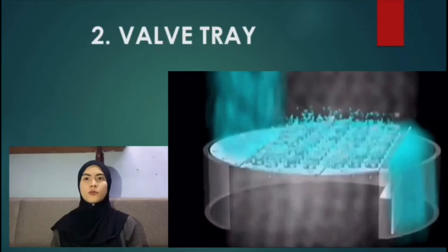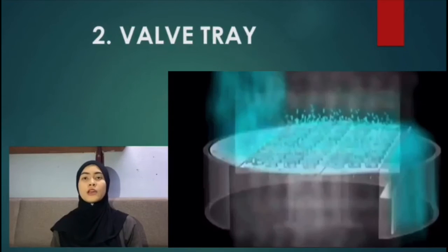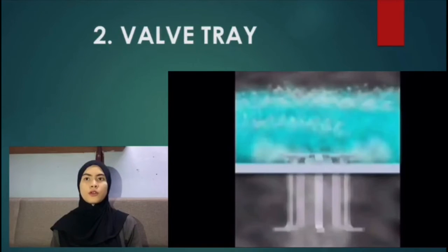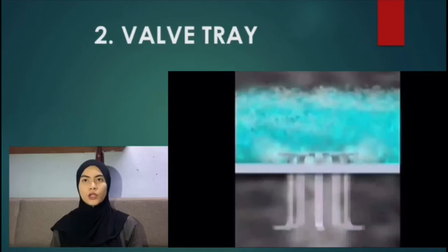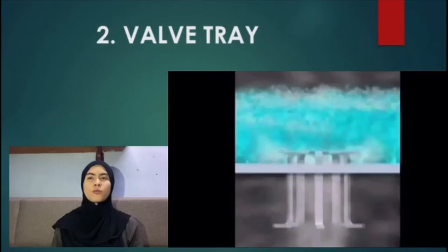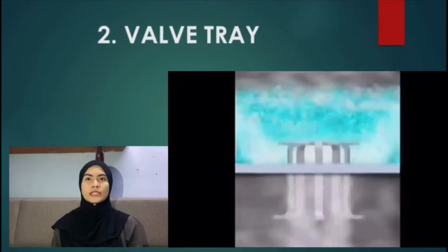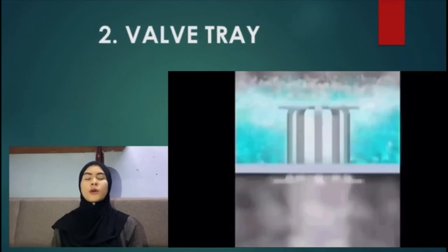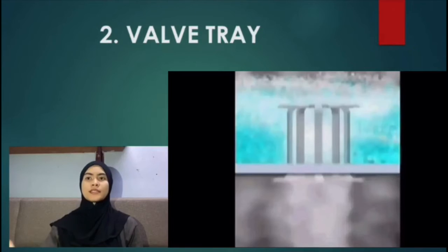each opening, providing a variable open area which is varied by the vapor flow, inhibiting leakage of liquid down the openings at low vapor rates. Hence, this type of tray can operate at a greater range of flow rates than the sieve tray, while costing only about 20% higher than a sieve tray.